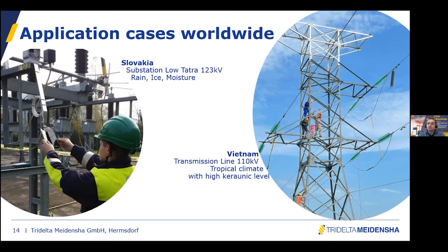So all the typical cases are covered, and of course we can install it on a 33 kV arrestor, just as on an arrestor on the 110 kV line. The voltage doesn't play a big role in that case, and the precision is the same. So if there is a necessity to monitor arresters of medium voltage, then yes.